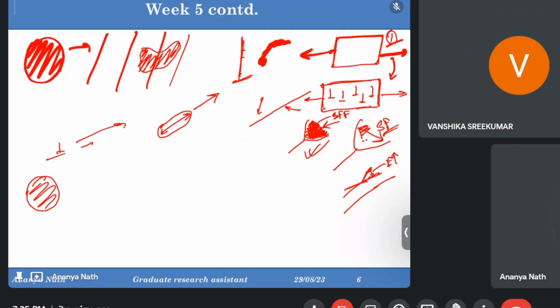Ma'am, actually, the two grains are equivalent. If there is a grain boundary between two grains, and there is some misorientation of the boundary between these two grains, then after lattice rotation, if these grain boundaries completely match with each other, then nucleation will start.